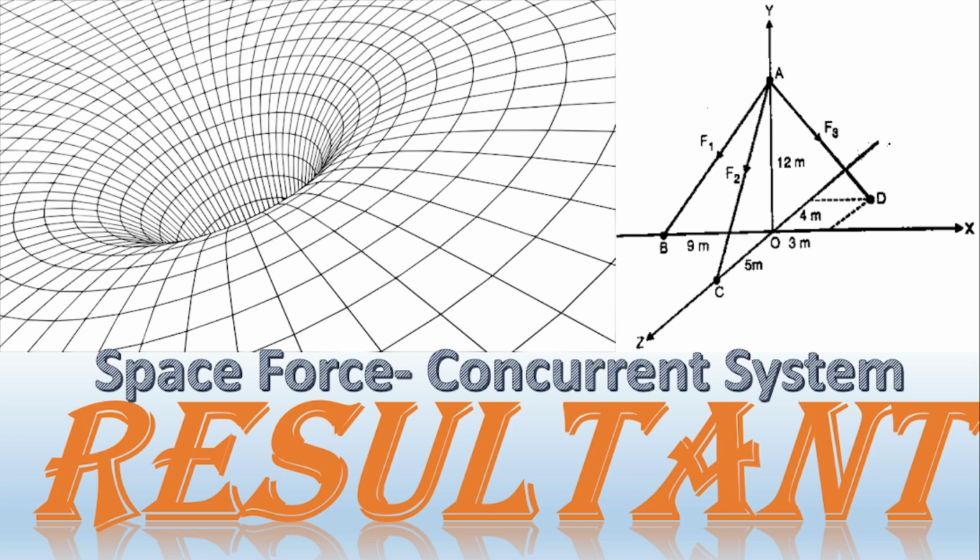We'll discuss how to find the resultant of the concurrent force system, then the parallel force system, and at the end the general force system. These three types are very important. These types are also there in the coplanar force system, and in the non-coplanar force system also we are going to discuss the three parts. Now a concurrent force system is one which passes through a single point. The line of action of all the forces passes through a single point.